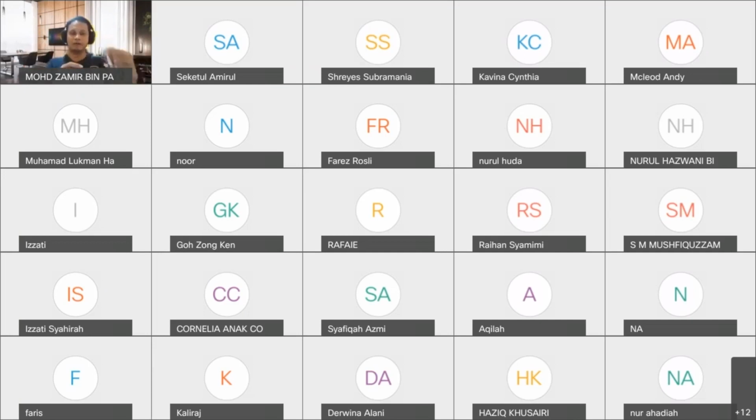you may, if you do XRD or Raman, for example, find 50 or 60% of your sample is crystal, and the other 40% is amorphous. In that case, we call it microcrystalline. So crystalline and amorphous are present together in one sample, in all locations across the sample. But when you mention microcrystalline, you have to mention how much is the crystallinity of your sample. For example, it's given by X subscript C, X_C equals 60%, which means your sample has 60% of crystal and 40% of amorphous.